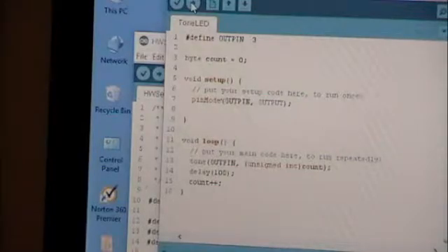If you go into Excel or an equivalent program, and you go across the top and say 0 to 360, so that you've got 360 points of the sine wave, and you say sine of, it's been a while since I've done this. If you do it so that you get the frequencies, sine of 10 hertz, and maybe sine of 30 hertz, and you run them off for each one so that they compress in, and you add them all together and graph them, you will get a square wave. I remember the first time I learned this in school, I was like, no way. And I went through and did it, and I'm like, what?